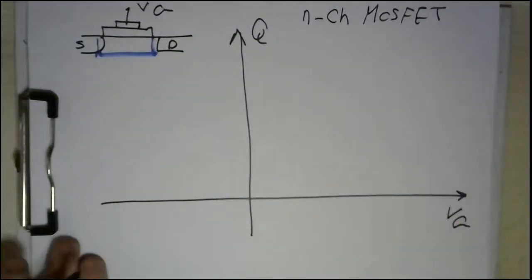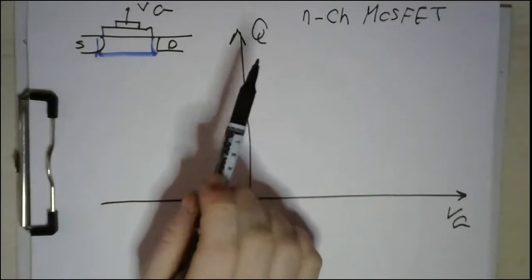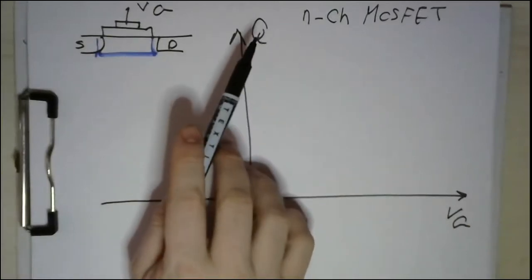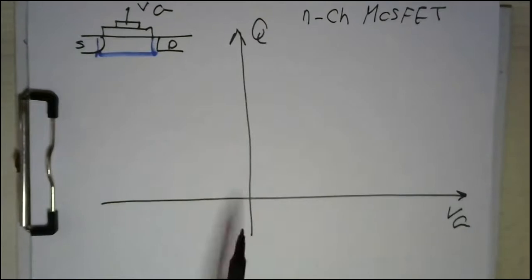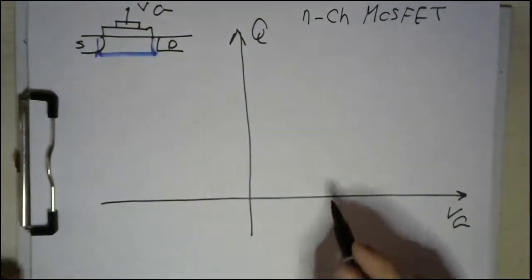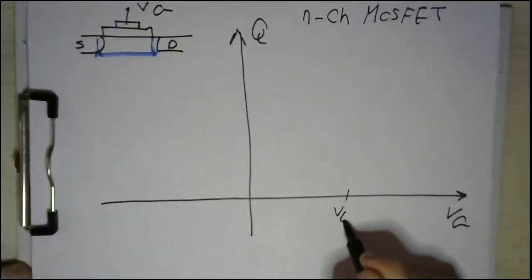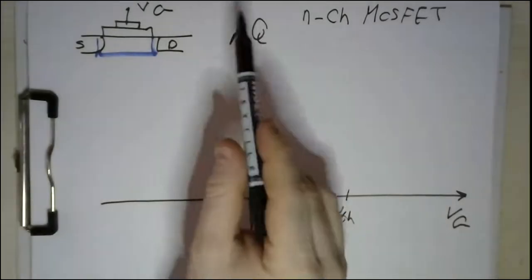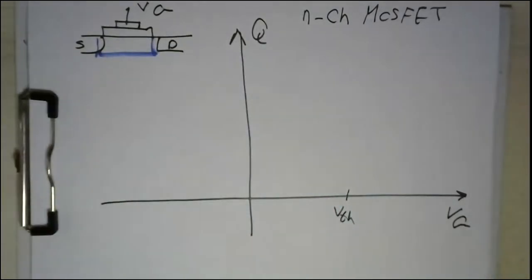So as this is an N-channel MOSFET, you should apply a positive voltage on the gate greater than the V threshold in order to create this inverted N region. What if you insert a negative voltage? We already focused on this in our previous part, if you remember. You can return to it if you forgot. This is what's called the accumulation region.